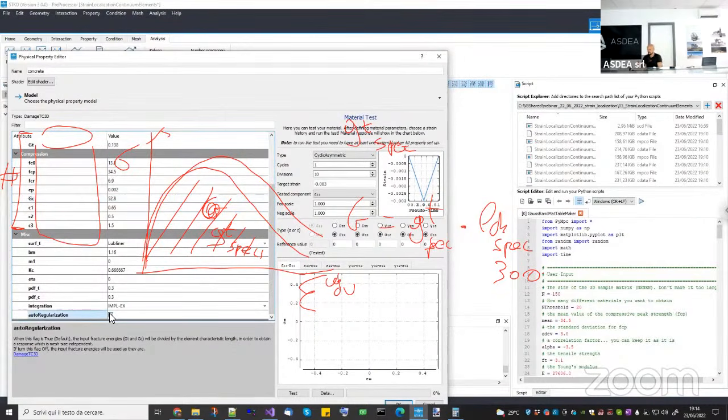And what it will do basically, my material model will take this G and it will compute a small g, so a specific fracture energy, but specific to my element, which will be G over LCH of the element. Now, if you develop this one will be equal to GT specimen times LCH of specimen divided by LCH of the element.